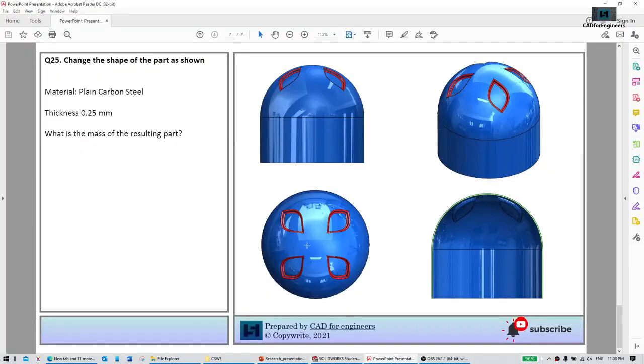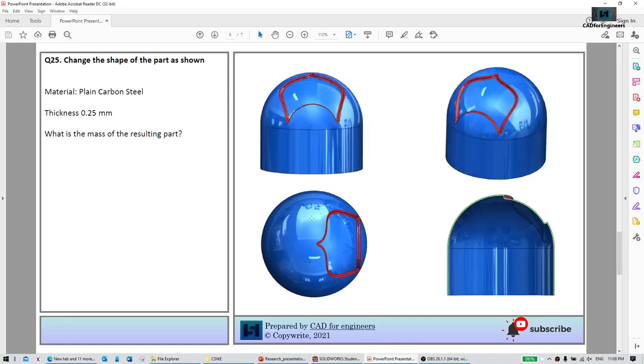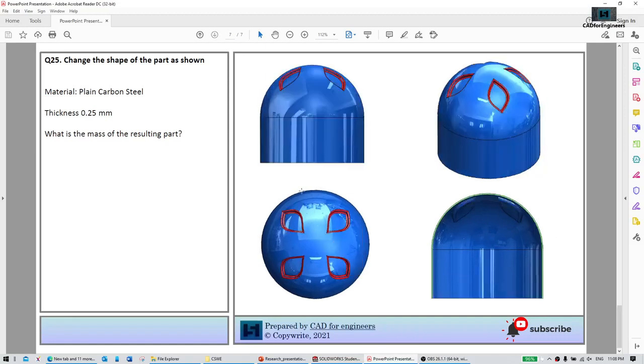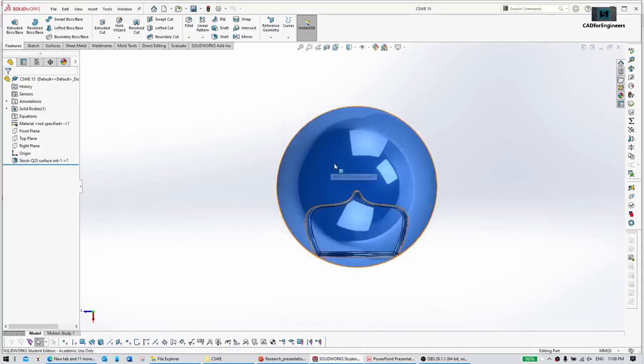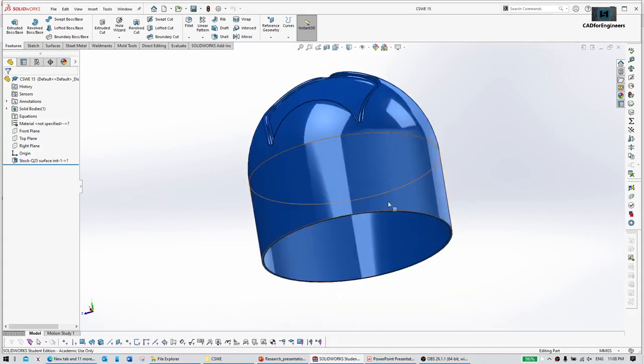And since you see that, first try to analyze the pattern. Over here you have this single pattern, and you have multiple patterns of the same type of shape. It means this part was created using a circular pattern feature, right? Keep this in mind. And if you have a shelled part, first try to get this shape back into a full solid body. Try to do that first. Let's go ahead and try to see that, and then I'll go back and analyze our part.